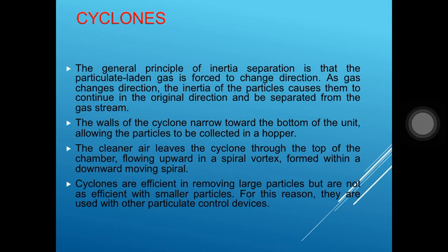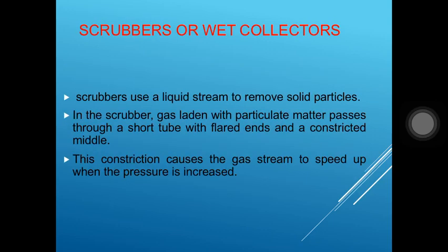Cyclones are efficient in removing large particles but are not as efficient with smaller particles. For this reason, they are used with other particulate control devices. Next is scrubbers or wet collectors. Scrubbers use a liquid stream to remove solid particles.